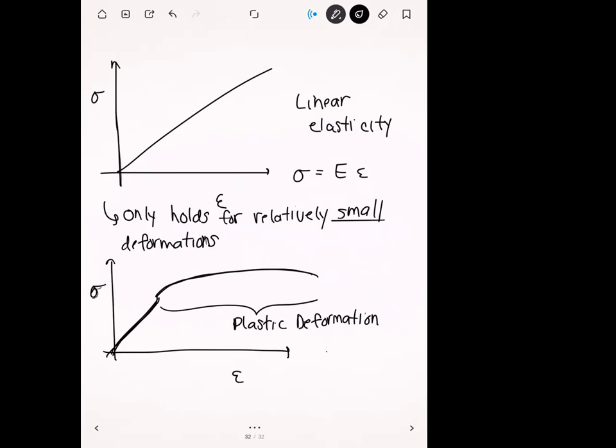And so if you're running your finite element simulation and you notice that the deformations look fairly large, right? And so you look at the values for deformation, you say, that looks pretty big compared to my model. You might have to start looking into plastic deformation because if you don't explicitly turn this on, ANSYS is not going to actually account for that for you.